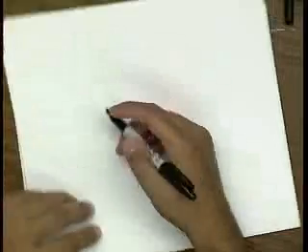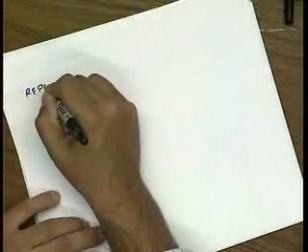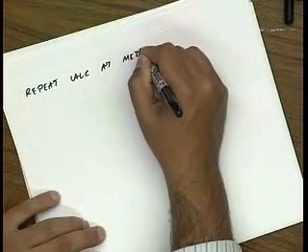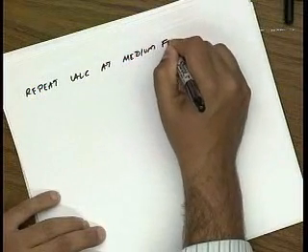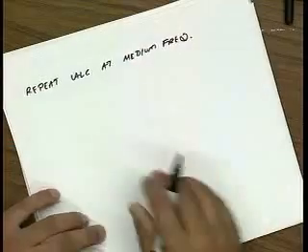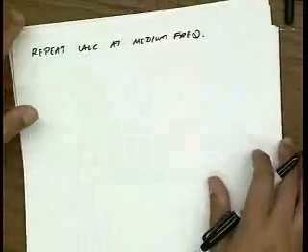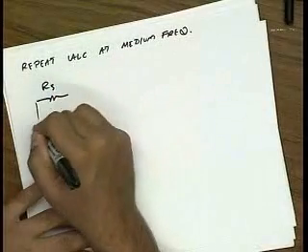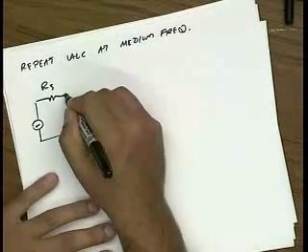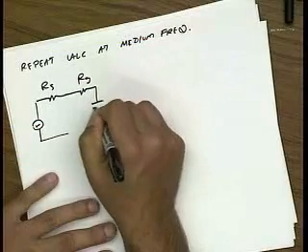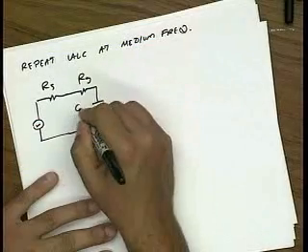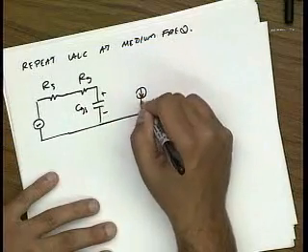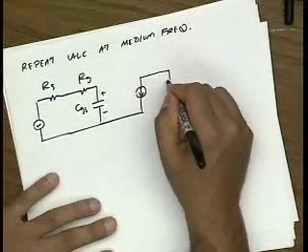All right, so let's repeat the calculation at high frequency. Let's say at medium frequencies, because high frequency always means that your equivalent circuit gets way too complicated, so it's not very pleasant. So here's RS again, here's the voltage source, here's RG again, here's CGS. Again, we're at medium frequency, so for simplicity, we're going to neglect C mu.